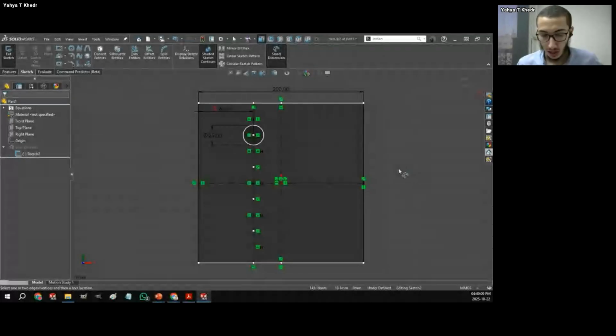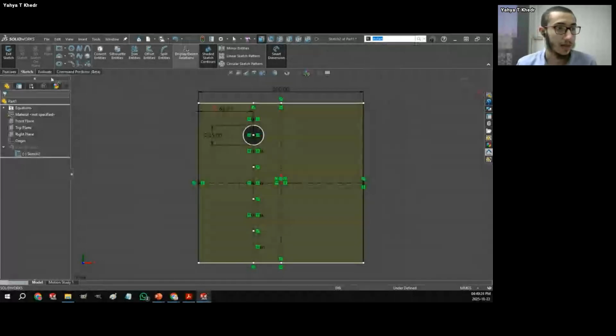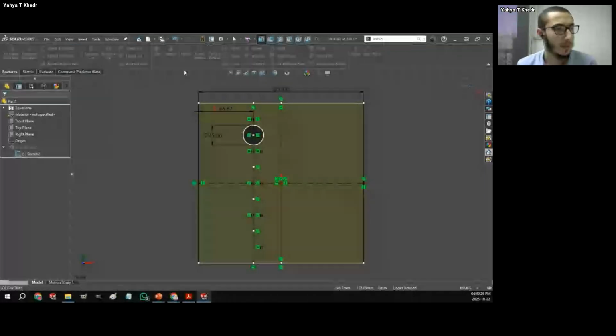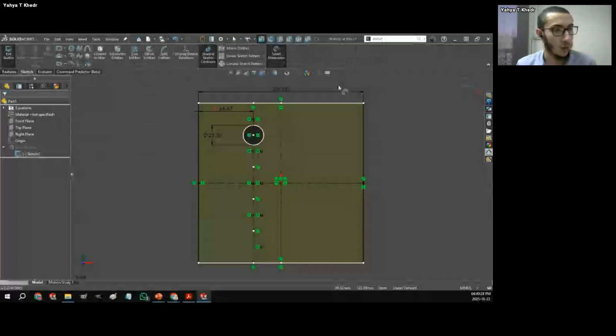Okay, someone is asking, can turn on 3D? Simply search for instant 3D and just click on it, just like that. Now it's off, and if I go ahead and click on it once again, now it's on. You might also find it in the features tab over here, but I prefer to remove it. You also have instant 2D, which will do the same thing for sketches. I prefer to have them on, but it's obviously a personal preference.